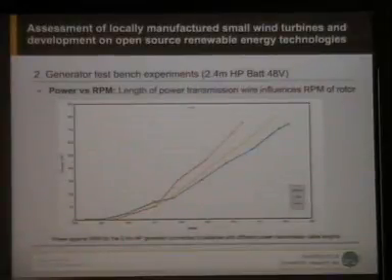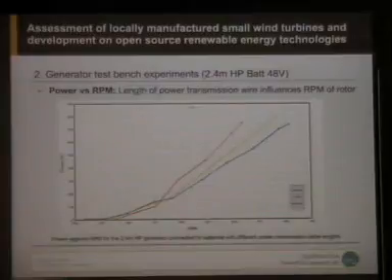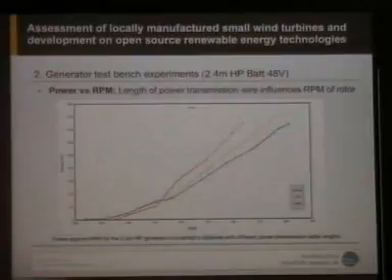This concept we have integrated into a software program that we'll look at on Thursday, which is the connection of the generator to the batteries. We run an optimization that tells you what kind of air gap and what kind of cable to use to be as close as you can to the maximum power curve and increase the energy production. It's a low-cost way of doing that. In the end, you might want to go 100 meters from the batteries, and it turns out that you can do that with a very thin cable, because you're introducing resistance, and the whole thing is producing much more energy in the end.